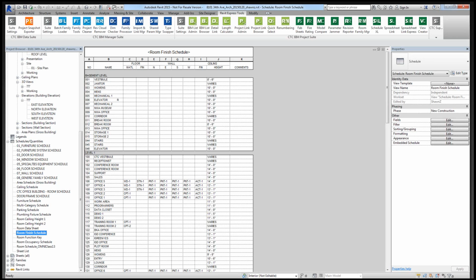In fact, you can even do concatenation. You can do formatting of multiple strings pulled together. So if I wanted to say, for example, in the electrical voltage parameter that's pre-existing, that's text, I could say with a text string, it's 208/120, parenthesis 3 or parenthesis 1 or whatever I wanted for different phasing. So I could actually fill out that voltage text string with something that way using, again, Excel and formatting it from other properties on an object.